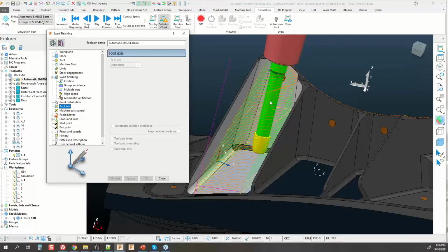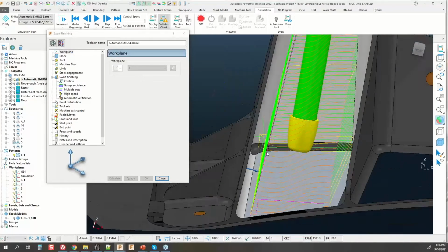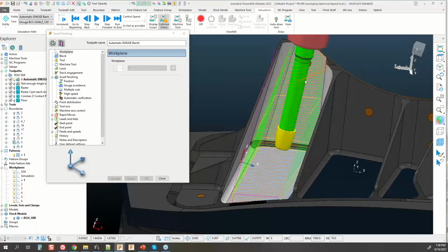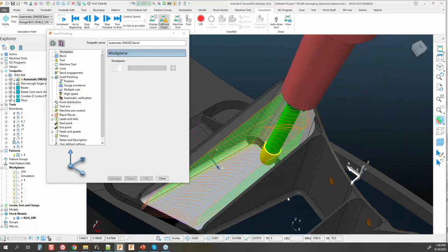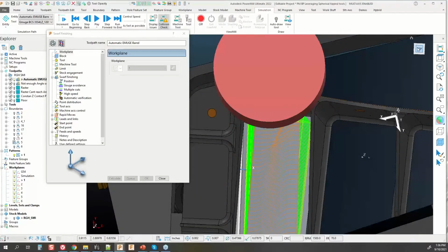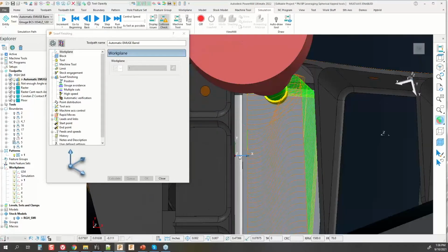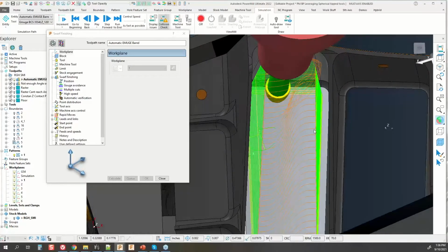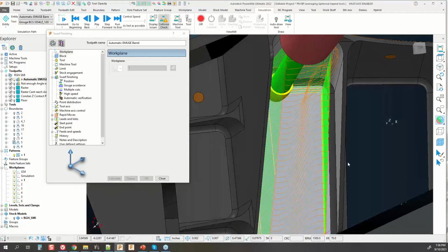Prepping for the toolpath, before I jump into that, I usually always create a work plane pretty close to my main plane that I'm trying to reach down into the geometry. This can help you on the onset so that you don't have any issues reaching down into cavities like this. All right, so you create your work plane for your toolpath so that your machine can successfully tilt to the work first. If I look at the top on this, I'm averaging out the angle from that wall so that the majority of my undercut tilt is just on one side.